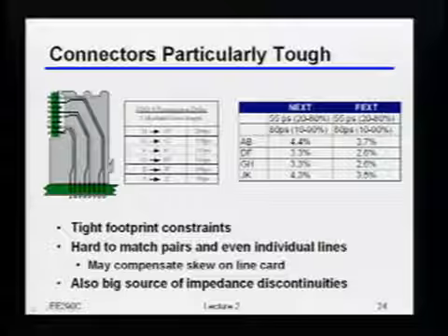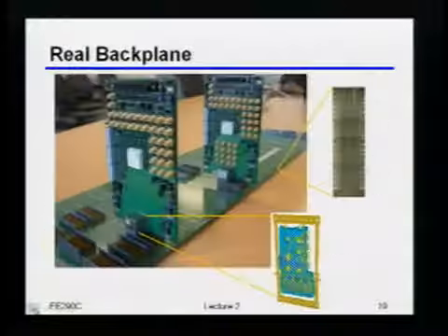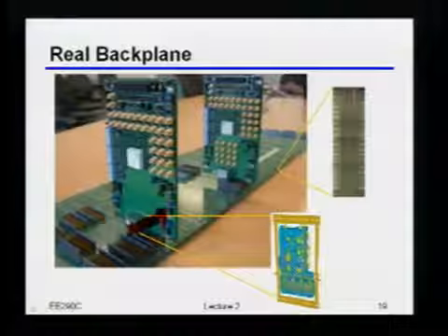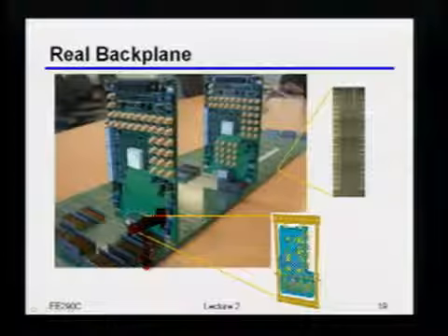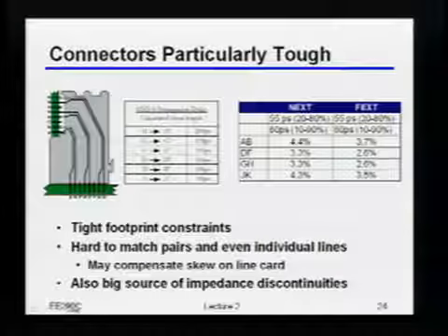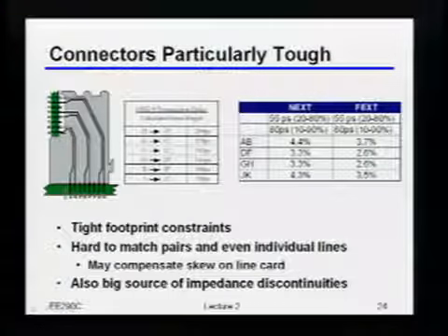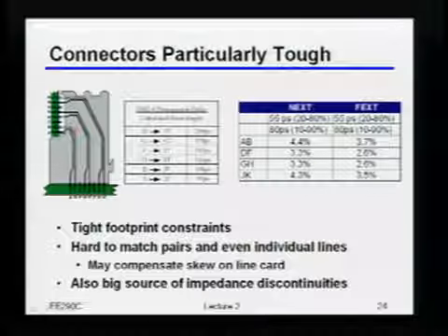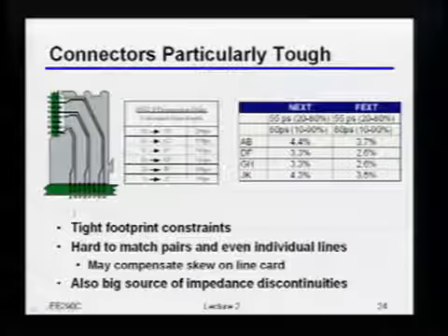You can see, just as an example, if I want to do one of these things, and I'll go back to the picture here, where I've got the board sitting vertically like this, and then I plug the connector in that way into the daughter board, but I want it to go down into the backplane, I have to do this weird transition thing, right? And so what you can see is usually the people who have to do that do these weird bends and splits to break back out into the PCB pitch. So you may have one pitch on the PCB, but in the connector you want it compact, so you bring things in together, then fan it back out. Again, it turns out really tough to actually make all these signals nice and balanced with each other, okay?